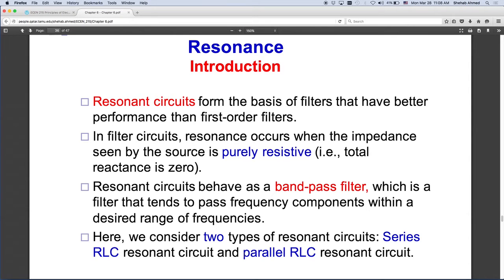What does that mean? There's less impedance now for the current to flow. The current was seeing an impedance, which is a combination of resistors, inductors and capacitors. At a certain value of frequency, the inductive impedance and capacitive impedance will equal each other in magnitude and be opposite, so they will disappear. You will only be left with the resistance, which means there is less impedance for the current to flow, so there will be more current at that resonant frequency.